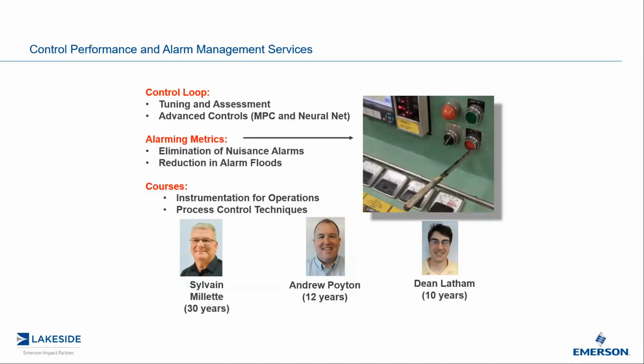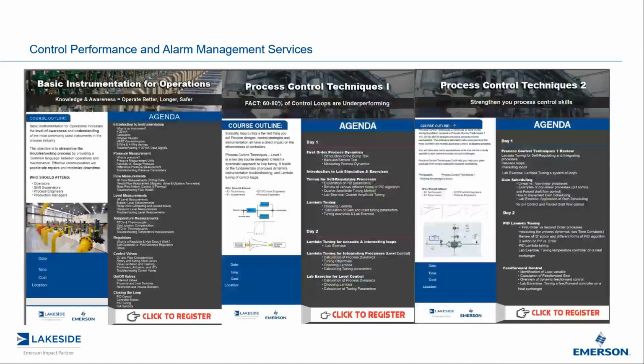And that's what happens when you cry wolf too often, is that we tend to ignore alarms, and that's when bad things happen. So we're there not to eliminate alarms, we're there to make alarms relevant, and reduce alarm floods, such as if a pump trips, do not alarm a low flow, do not alarm a low pressure, because they are redundant. Just allow the operator to focus on the root cause of the alarm. And that picture you see there is actually not a Google picture. It's actually a real picture that we took at a control room just to silence a particular alarm during a shutdown.